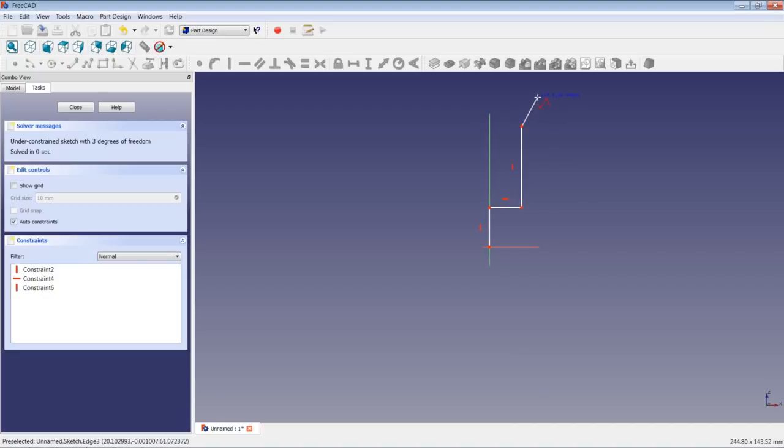Please note that by pressing M, you will change the behavior of the polyline tool. You press M once more, you could continue like this. Pressing M once more, continue arcwise, or like this direction, or press M once more, like here, or pressing M once more to continue like we used to draw. By doing a right click, you will end the polyline tool.